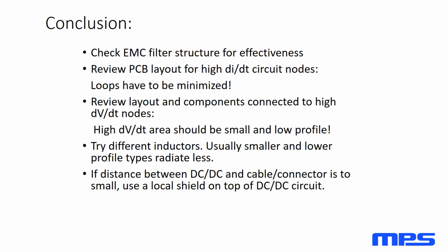Try different inductors. Try smaller ones, try lower profile ones. I know it's not always possible for optical inspection, but try inductors with connections on the bottom side and see if that helps. And check the distance between parts, right? We'll look at a design tomorrow where it's one-sided in terms of component placement. If we have a very, very small board, and I have a customer that designs boards that are maybe 2 inches by half an inch wide or 1 inch at best, they do have to use a shield because everything's so small, everything's so compact.